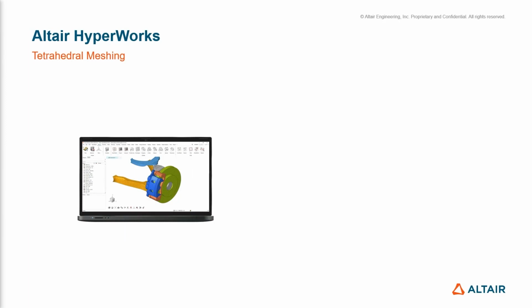We offer quick and easy workflows for tetra meshing with methods appropriate to your requirements and meshing standards. The first method is accessing the Tetra tool in the Mesh ribbon, where we can quickly generate tetra mesh from closed volumes of shell elements or from solid or closed surface geometry. We can also quickly remesh to regenerate and refine particular regions of our models.